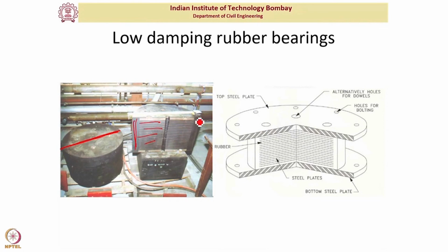Remember, in the end, what you see here is basically a rubber cover. The cover is provided to the rubber bearing to protect against debonding at the interfaces, because it is very vulnerable at those points. And sometimes you might see a central hole.